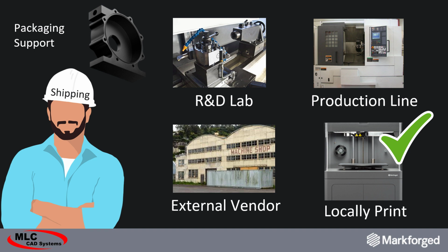By using an additive manufacturing solution for little bits and bobs in packaging support like that, a couple things happen. One, they fit exactly on your part, meaning you're not compromising, you don't have to tape that thing on. It'll snap right on and fit really well. But also, those packaging support pieces can be printed whenever, however, and that gives a lot of flexibility to that additive department. And so when they don't have quite as many things to print, they will throw a handful of those things on there and they'll optimize their cycle times. So in other words, if you've got a print that's going to take 14 hours, it's going to take through till tomorrow.